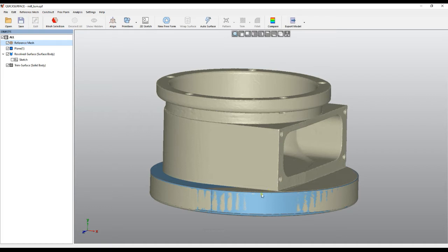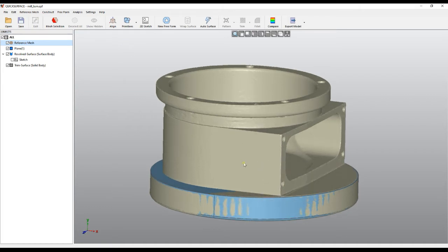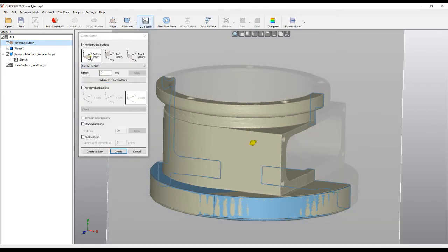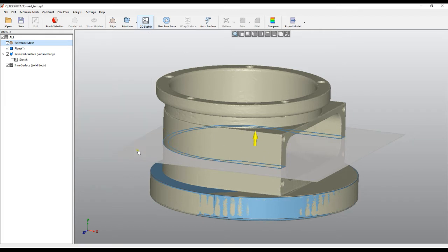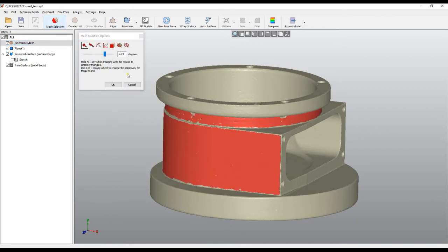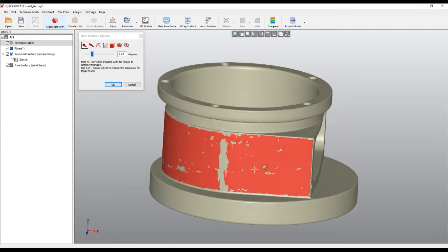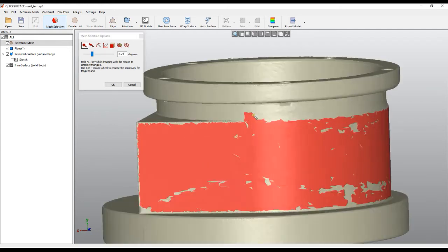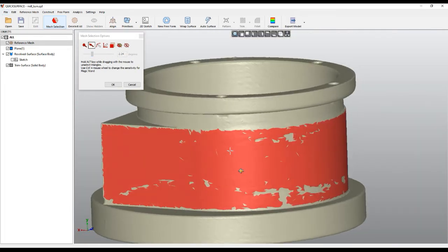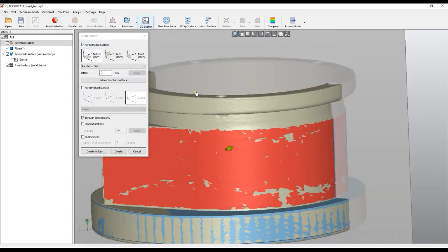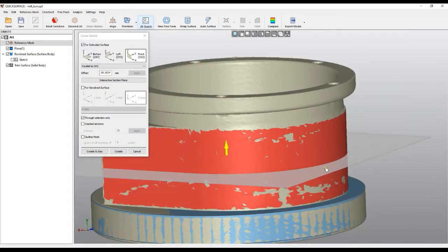So I will start reconstructing the top, and the normal way would be just to create a 2D section which is aligned like this. And I want to create multiple stacked sections and get them through the selection. So let's quickly get this area. We'll just use the magic wand to select what I want. This is enough. Even if I get more, I can just use the Alt key and remove this selection as it's not needed. I press OK, and now I create my sketch, which is parallel to the plane XOXZ.